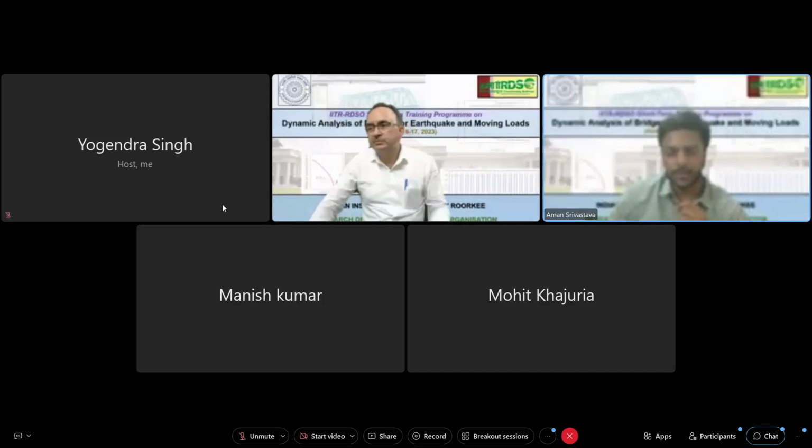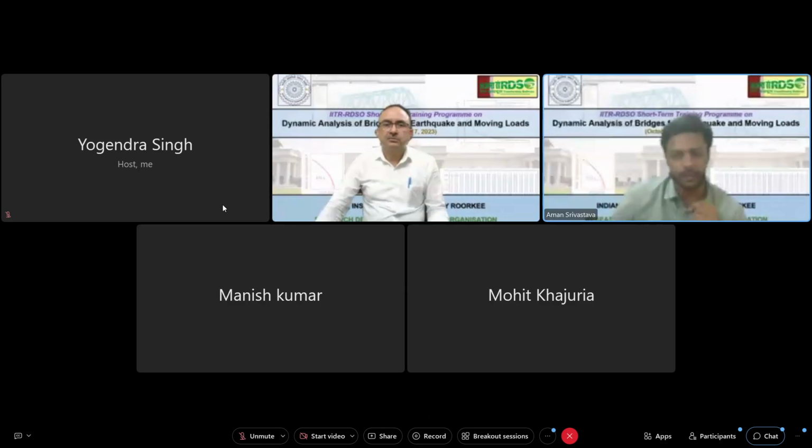Mr. J is asking, we are required to ensure no collapse under MCE. However, under ULS, we are checking for DB. How are we ensuring no collapse under MCE as per Indian standard? Actually, we are not doing that. Under any code, we are not doing that. The current framework of all our codes, which is force-based design, can't do it.